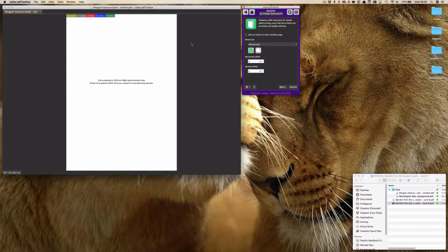So that would make it easy in an automated workflow to take 10 incoming PDF documents, merge them into one single PDF, and then run one of the impose actions to do the actual imposition on the PDF document that was created out of those different incoming PDF documents. But the engine itself in pdfToolbox will always take one incoming PDF, it will do something with that, and it will generate an outgoing PDF.